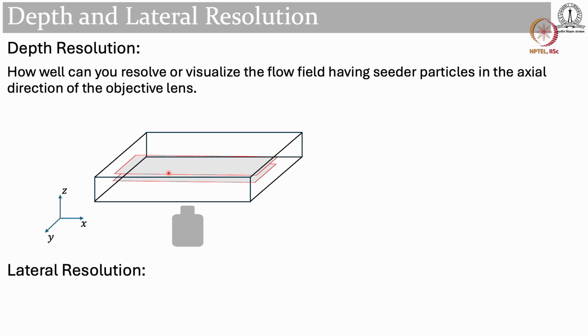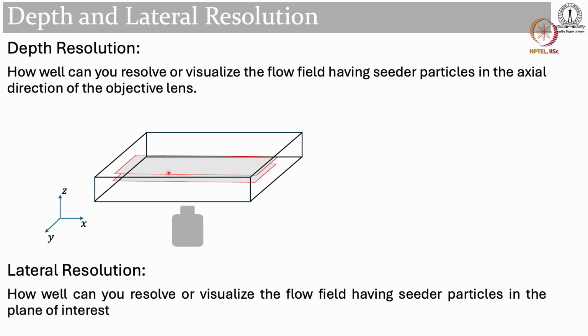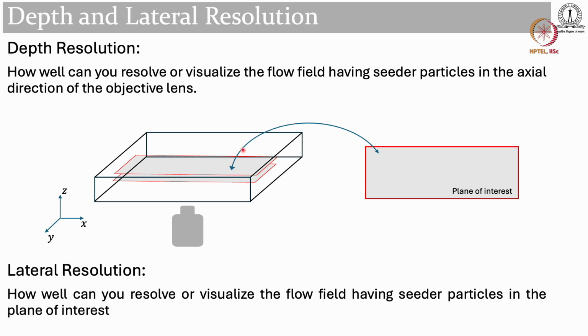The other thing is the lateral resolution. By lateral resolution, I mean how well you can resolve or visualize the flow field having seeded particles in the plane of interest. If this is the plane of interest, how well can you resolve the particles using your optical system in this plane? You can see two vectors popping up here, and how much distance you can get between those two vectors, or how well you can resolve the vectors.